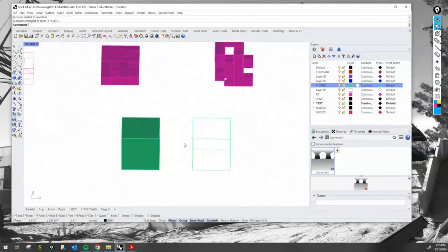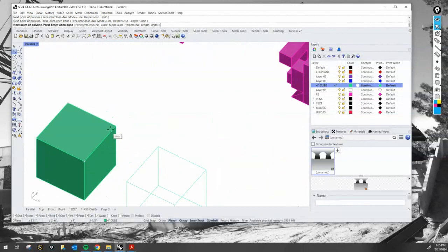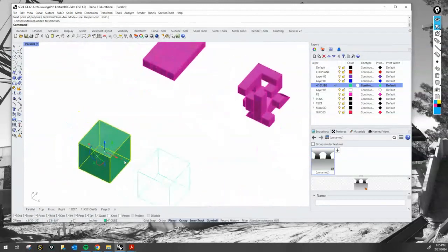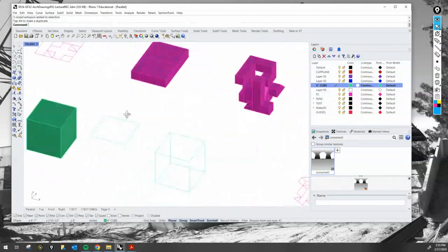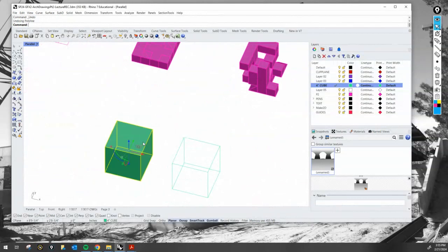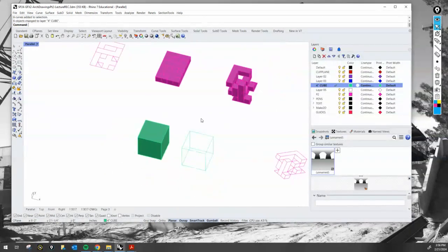So it's the wireframe, meaning that if I was to grab, and let me get myself on that layer, activate that layer. If I was to get myself, say, a polyline, and I was tracing it all around, clicking and clicking right here, I'm tracing the outline of that shape, right? But we have a command that actually can do that for us, which again, I'm going to undo this so I can delete this. That actually helps us do that.